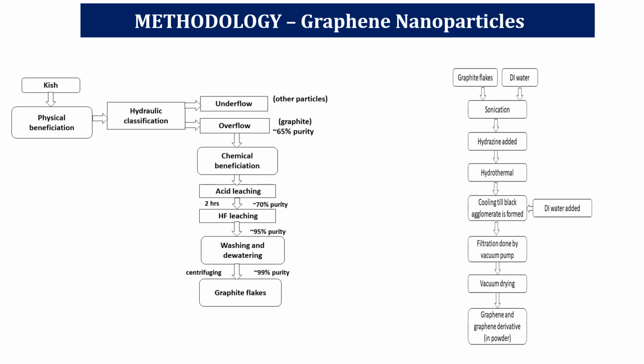As the iron cools during tapping and transport to the steel shop, it becomes supersaturated and carbon comes out of the solution as flakes of graphite that float to the surface of the iron. The hot metal is usually transported from the blast furnace to the steel shop in a refractory-lined torpedo ladle. The longer the hot metal is held, the greater the cooling and the greater the yield of graphite. So from here we get the graphite flakes.